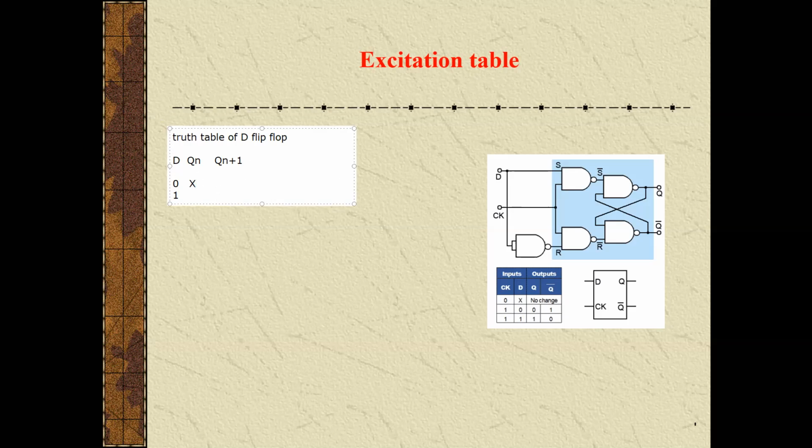It may be low, or it may be high. So based on that, the output will be available. Similarly, for the high signal also, we don't know what the present output at the terminals is, so we will assume it's predefined. It may be 0 or it may be 1. In sequential circuits, the output depends on both the combination of the input and the present state. So according to that, the next state will be available.